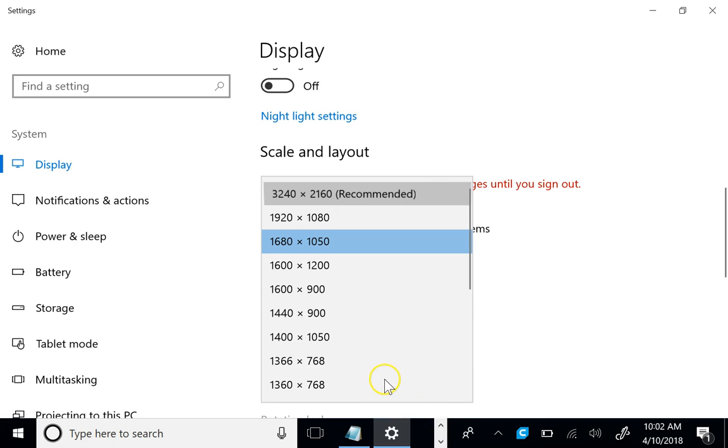Okay, so I have my little STL file here, which is mega tiny, right? And you could, like, oh, I screwed it up, go back to CAD, scale everything up, re-download it, reopen it, or you could just grab the scale function in here and be like, yeah, I'm going to need to scale this a lot, right? Oh, and you'll notice here, down at the bottom, it says it already scaled it to 10,000%. So I lied to you when I said it was a millimeter by a millimeter by a millimeter. It was like a nanometer by a nanometer by a nanometer or some tiny little bit.